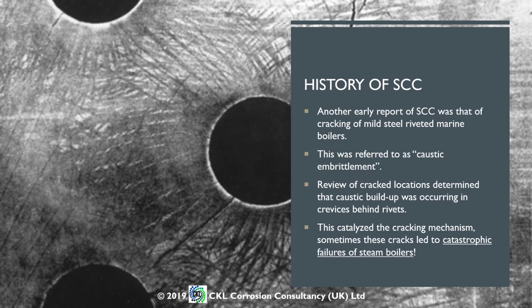Then you have a hot surface, and you have stresses around the aperture through which your rivet is fitted. You've got internal applied stresses as well on the boiler because it's containing pressure, and then you have what's needed to drive a stress corrosion cracking process.